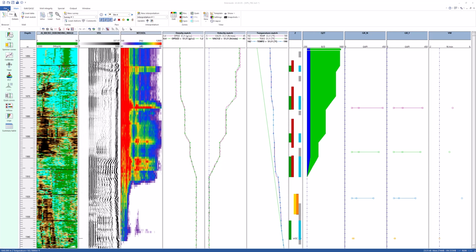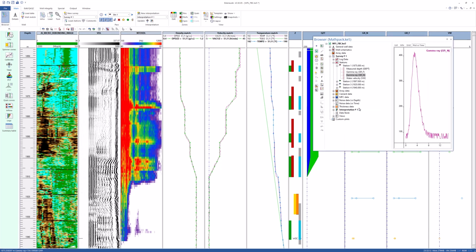Water flow logs are pulsed neutron measurements based on the oxygen activation principle. In a water hydrocarbon environment, water is the only source of moving oxygen. A burst of neutrons activates the oxygen, resulting in an excited state. The oxygen returns to a normal energy level by giving off gamma rays.